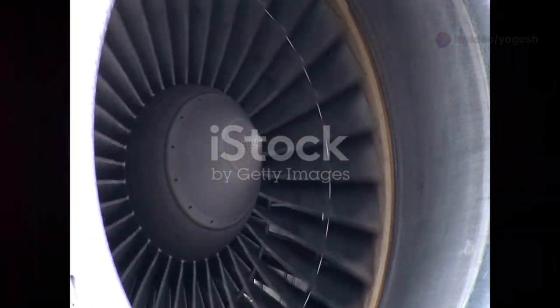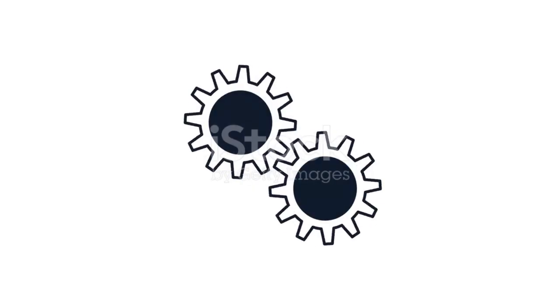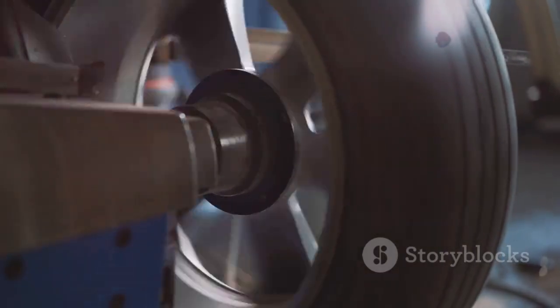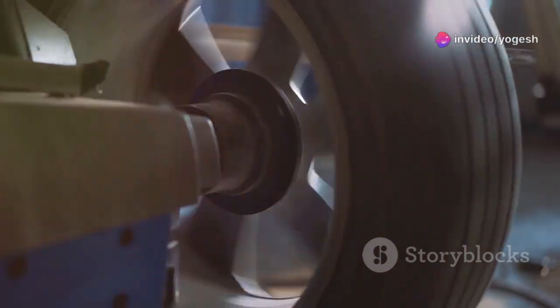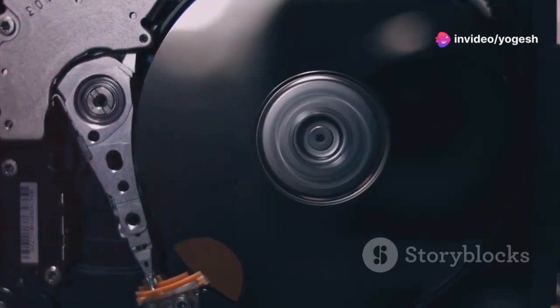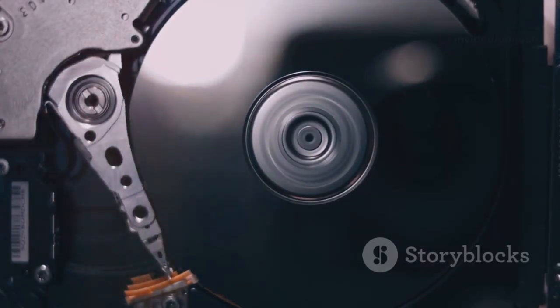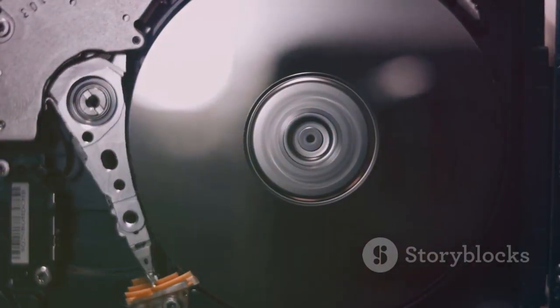Why is concentricity so important? First, it ensures smooth rotation. A wheel that isn't concentric with its axle wobbles, wears unevenly, and causes vibrations. In high-speed parts, like turbines or hard drives, perfect alignment is critical for balance and efficiency.